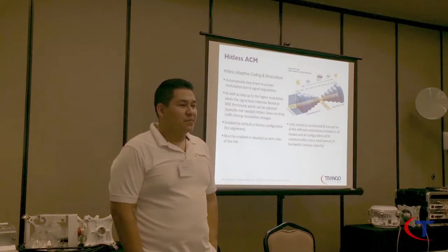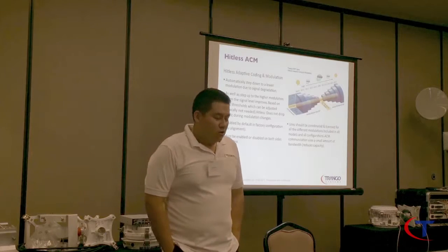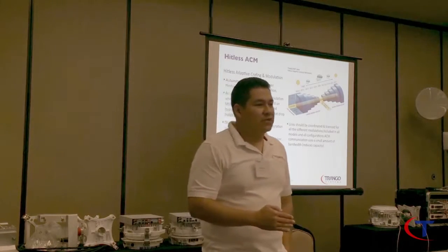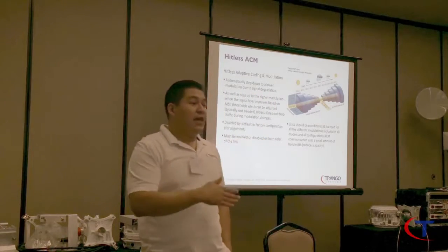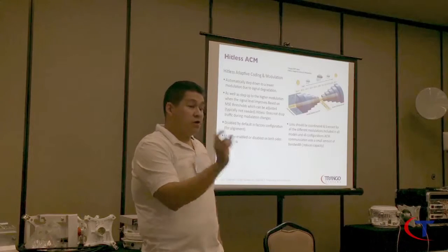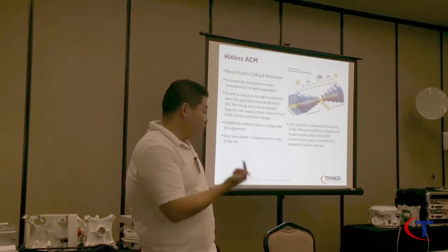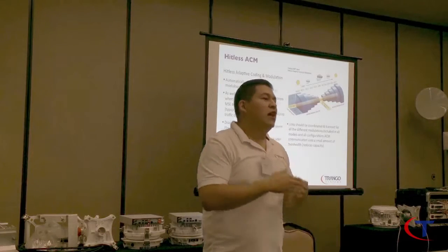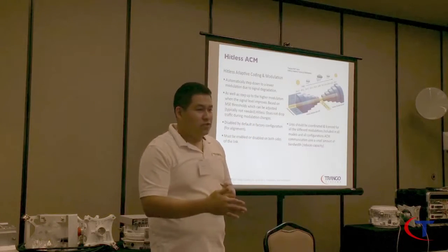Are we just thinking different now? In the past you had a fixed modulation speed channel. So ACM went up and down, and before you had speed, channel bandwidth, and then your fixed modulation. In the new radios, you have a max modulation and minimum modulation rate. So now the radio can play between those modulation rates.